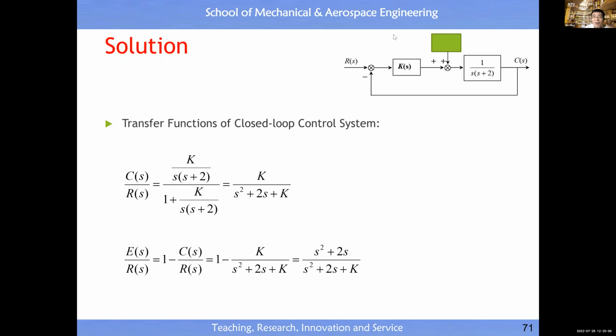All right, first, now here you see we consider this 2 input single output MIMO system as a sum of 2 SISO systems. When we study this one, we just ignore disturbances. Okay, so we separate them. Okay, we have 2 control loops of SISO, single input, single output. Then what is the equivalent transfer function? Forward branch over 1 minus the loop transfer function. Simplify it, you get this one.